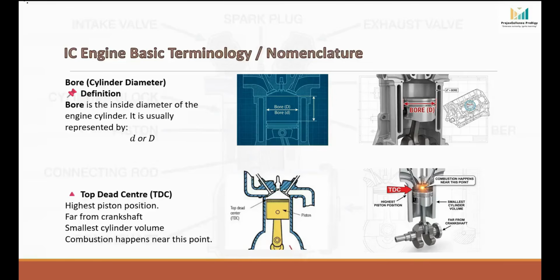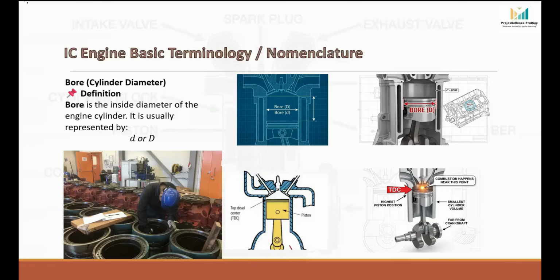As a result, the cylinder diameter gradually increases. And this wear is not uniform. Usually, more wear happens near the top, here, and on thrust sides, and in the piston ring travel zone. So the cylinder may become oversized, oval in shape, or tapered from top to bottom. So during engine overhauling, we check diameter reading and ovality. Normally, bore gauge is used to measure the bore diameter.